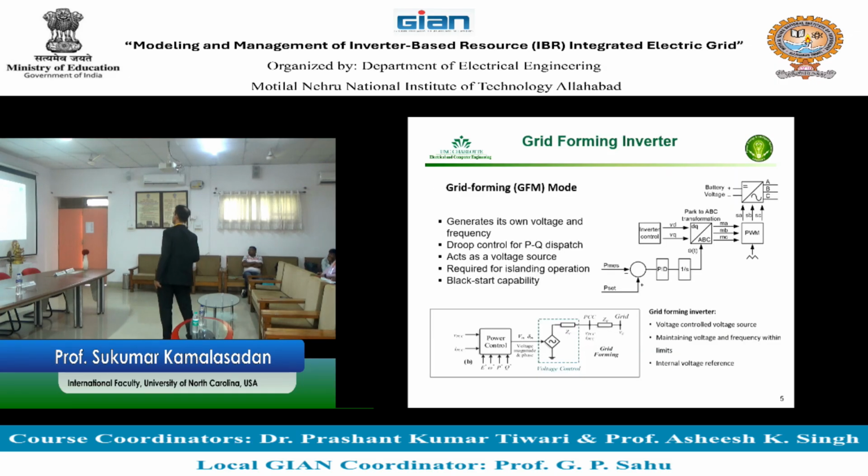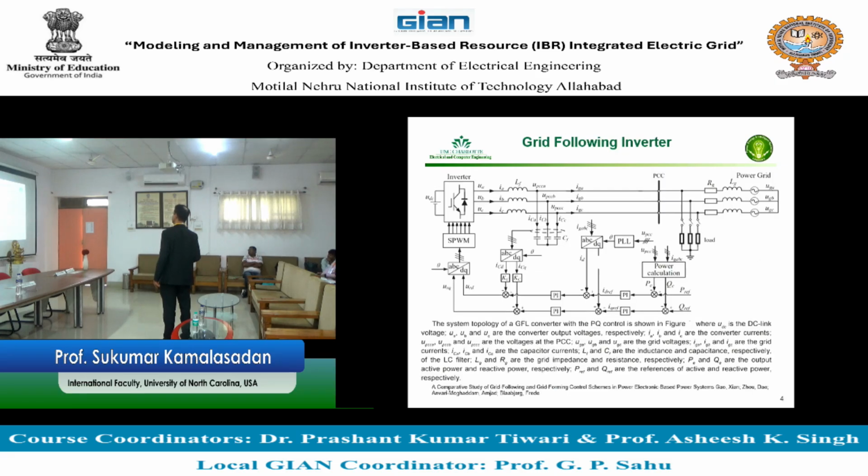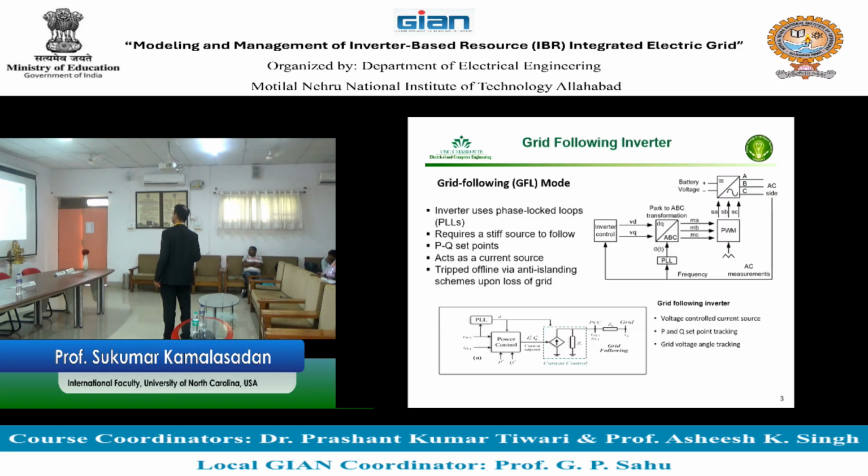So the grid following mode is basically like this. In grid following mode, you can say that it has a voltage and current, and a power reference given from the grid, and then you follow the power reference based on the angle you calculate. In such a grid following operation of the inverter, mainly the inverter's job is to push the power. So the inverter can be generally considered as a current source model or current source representation where inverters can push the power.